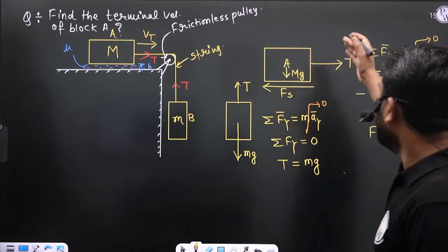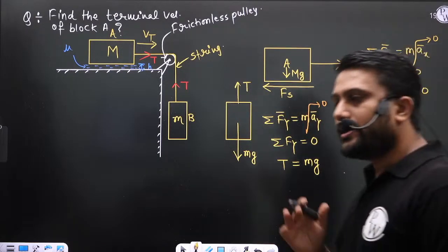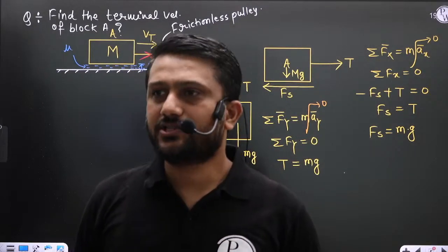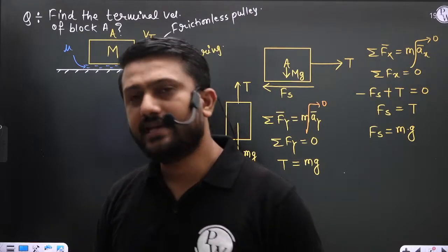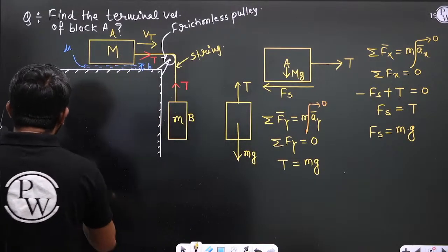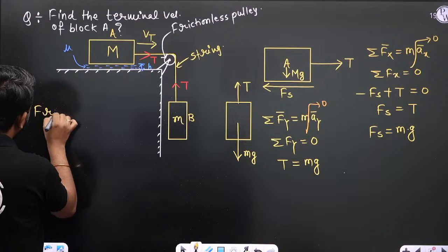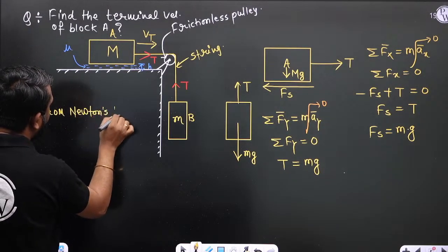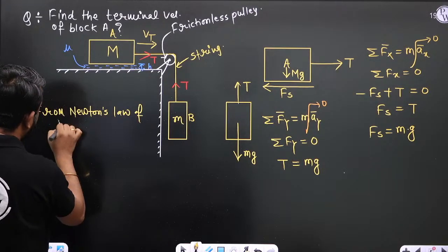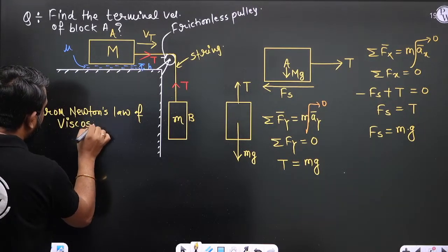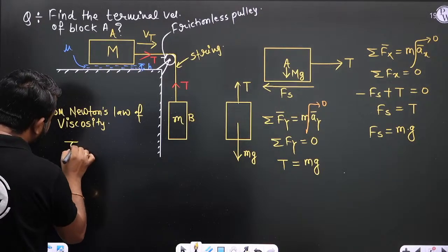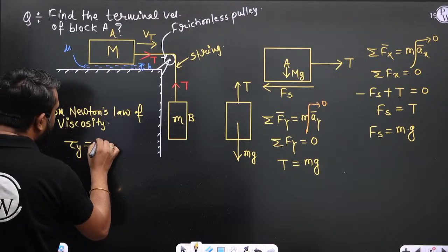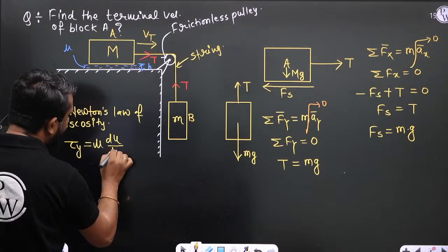So this is the engineering mechanics concept. Can we find out the shear force with the help of fluid mechanics concepts? So yes, we can find out. We know about Newton's law of viscosity. From Newton's law of viscosity, the shear stress at any layer is equal to mu du by dy at that layer,